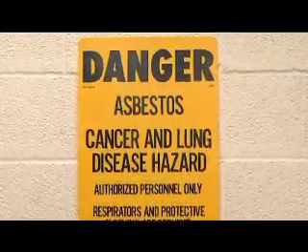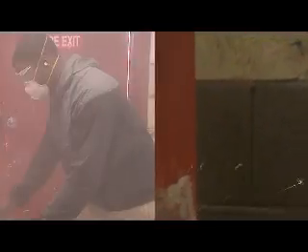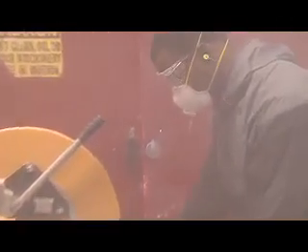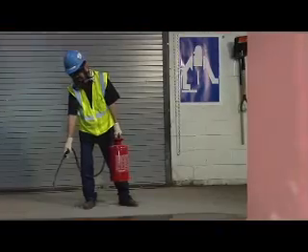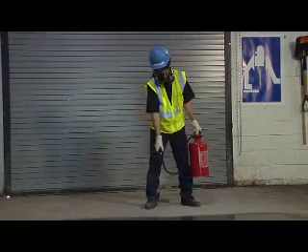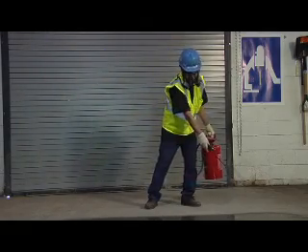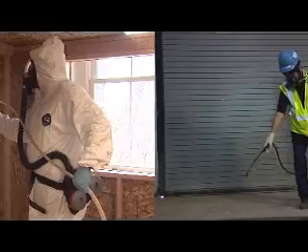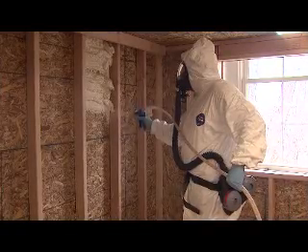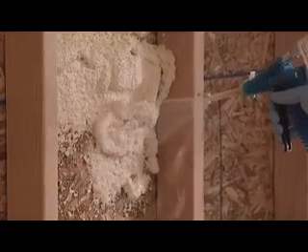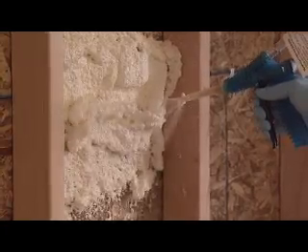breathe it in. More examples of respiratory hazards in construction include lead dust and fumes from grinding, welding, cutting, or brazing surfaces coated with lead-based paint. Silica dust from cutting concrete or sandblasting. Solvent vapors from adhesives, paints, strippers, cleaning solvents, and spray coatings. And isocyanate vapors from spray foam insulation and certain spray paints or coatings.